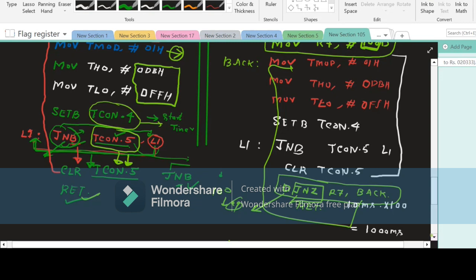Why lengthy, sir? Out of those 32 port pins, we have 8, 8, 16, 32 pins now. In LCD, we are using 8 plus 3, that means 11 pins in total. So one port and 3 pins of another port we are using. In case of an LED, we are using only one port, and out of that port, only one bit. And for switch also. But in case of a keyboard, we have to use more ports, and within those ports more bits will be used by us. This is the only thing we focus on.